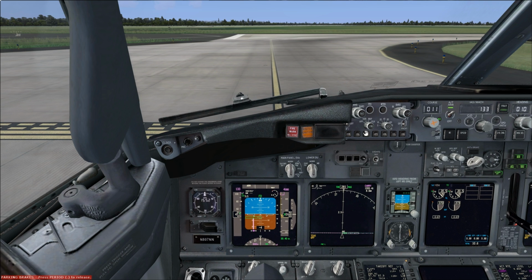Now, how do you recognize that you have entered a microburst? Well, it depends on where the microburst occurs. If it occurs behind you, then you'll notice a rapid decrease in indicated airspeed, and an almost equally rapid increase in ground speed if your aircraft has a ground speed reading. In this plane we do.